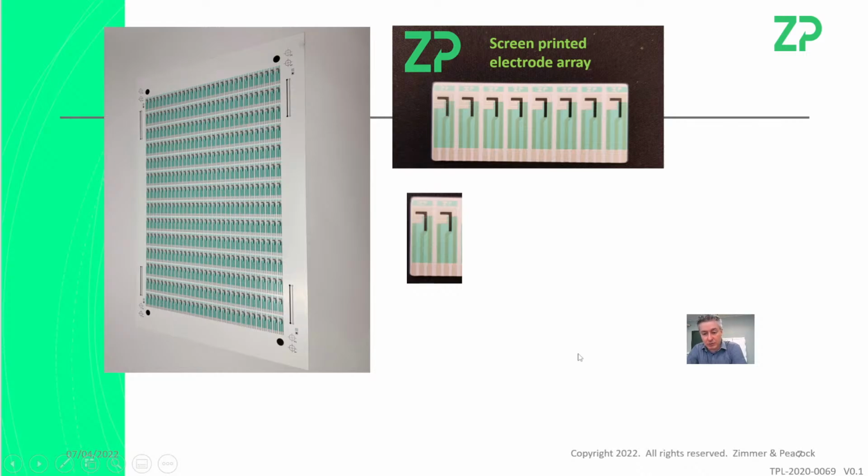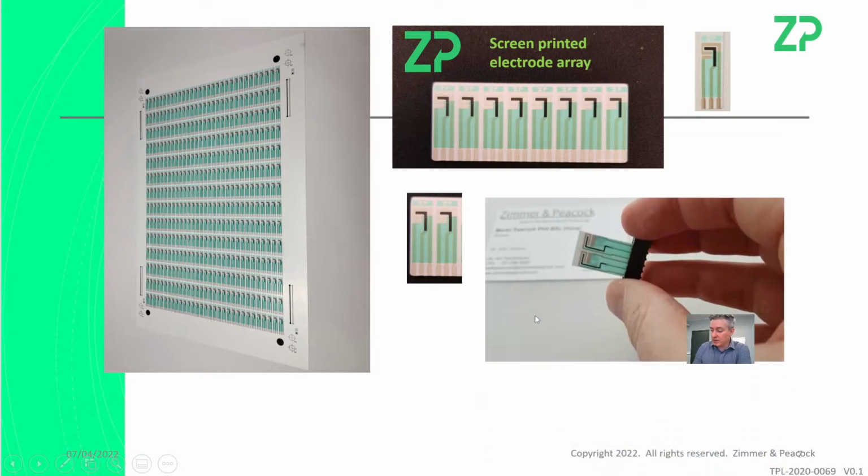So somebody came to us and said, I want 2 working electrodes. So I say, just take the sheet and cut them out in pairs, if that's really what you want. Or cut them out in singular. And I'm showing here that even if you want a pair, there's definitely connectors out there. There's connectors out there for a row of 8. There's connectors out there for a single one, and then there's connectors out there for 2. And I suppose it's because we're using a very standard pitch. What I mean by pitch is, on the electrical connectors, we have these little silver connection points, and they're all 2.54 millimeters separated from each other.